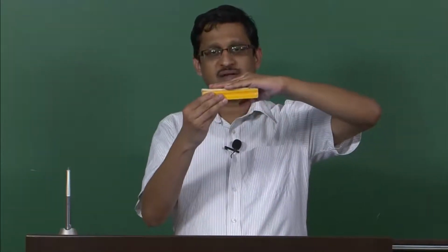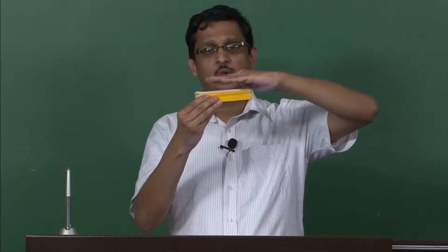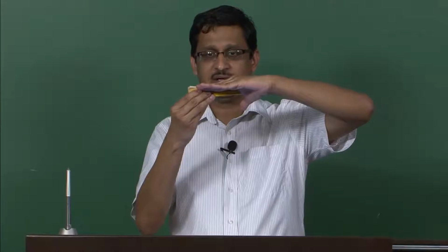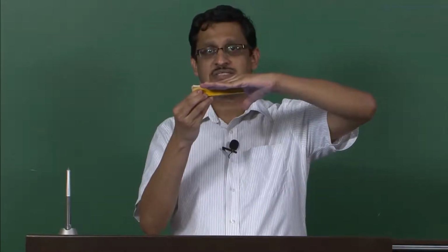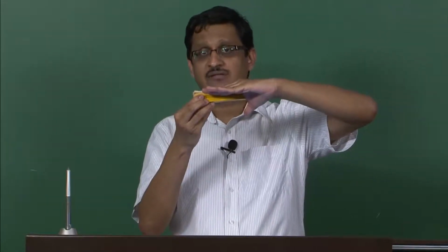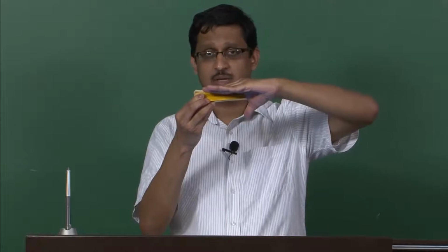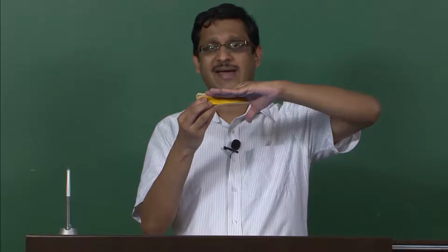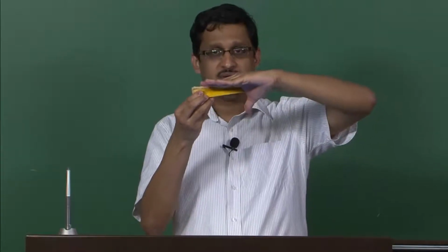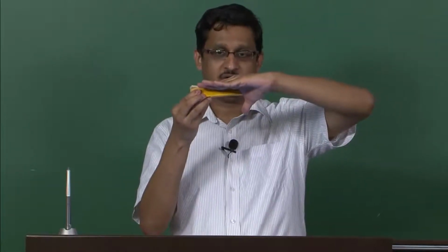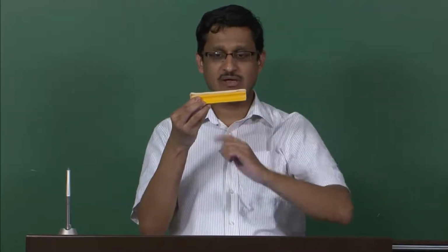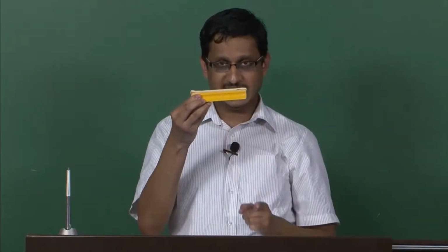Now, what happens as this wave begins to propagate? Well, you can imagine that as the wave begins to propagate, because of skin effect, the amplitude of the electric field starts to reduce as a function of z. So, it goes as exponential of minus z by delta. So, the length reduces and reduces, eventually tracing an exponential decay.